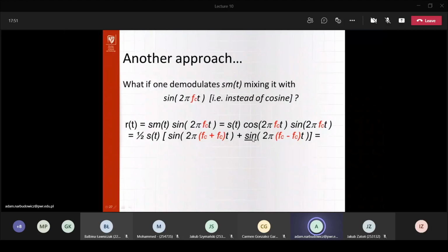So what's happening here is we get sine of 0, which gives us 0, which means that this component is cancelled. At the end, we get our signal s(t) multiplied by double the carrier frequency. So we are indeed creating harmonic components at twice the carrier frequency. However, then we multiply this with a 0, which means there is no DC component, because anything multiplied by 0 is 0.